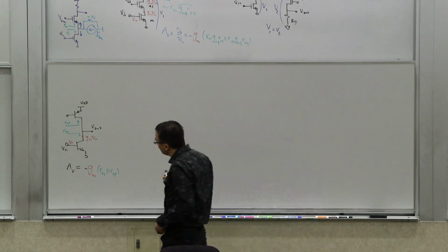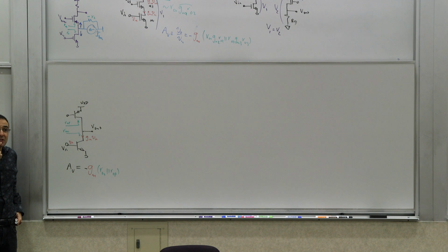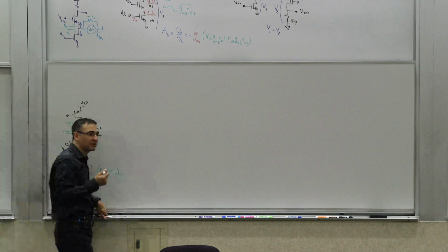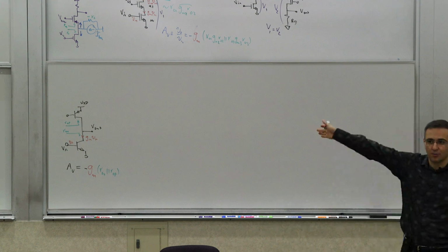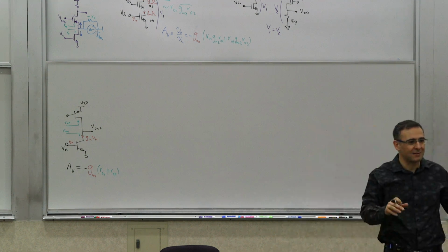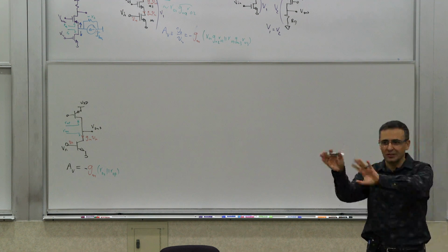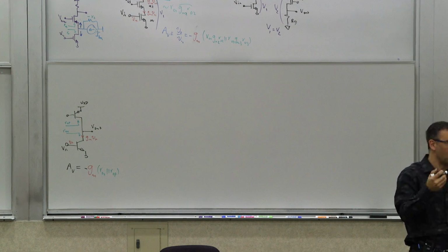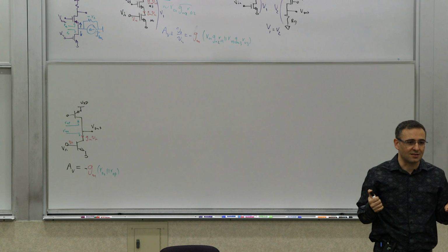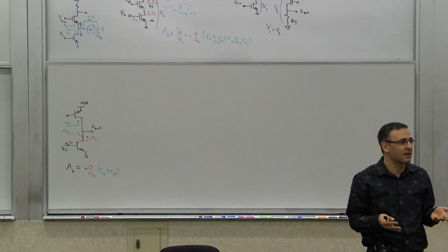Now, the other interesting thing is that this works if you have the complementary device, as we discussed. There are some cases where you don't have a really good complementary device. For example, we have talked about the bipolar process and the CMOS process as two different worlds. The way we deal with them right now is that we go to the bipolar world, we deal with bipolars; we go to the CMOS world, we deal with CMOS. But there are actually very commonly used processes called BiCMOS processes, which allow you to have both bipolars and CMOS on the same process.